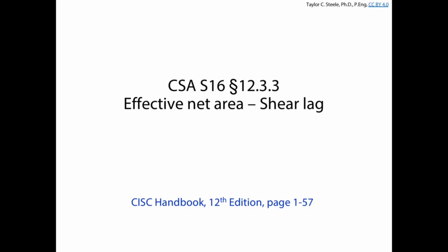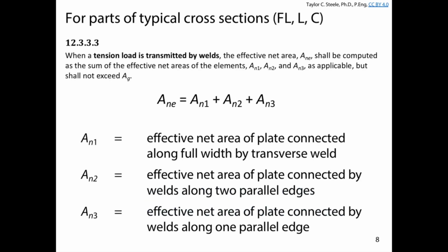So in CSA S16, we have clause 12.3.3. 12.3 deals with net effective area, and 3.3 deals with shear lag and net effective area specifically for welded components.